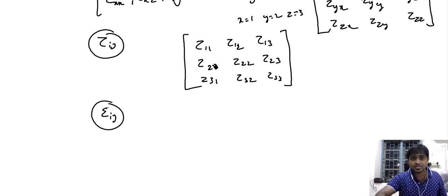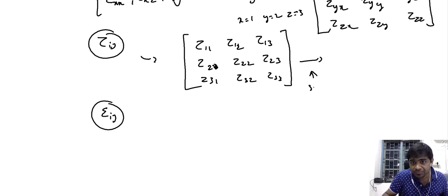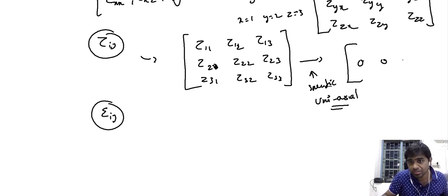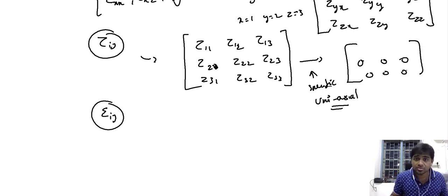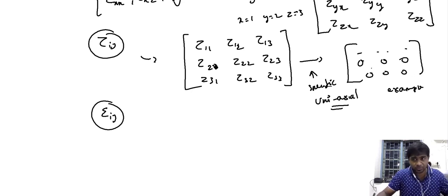Now, from this tensor representation, we can impose the specific case of uniaxial tensile loading, and correspondingly the matrix here would vary. Certain entities here would assume the value of 0. So when you focus on the uniaxial tensile loading alone, certain values here would assume the value of 0. And again, depending on which plane you are focusing on, certain entities would assume the value of 0, and there will be only a few non-zero elements, purely as an example.